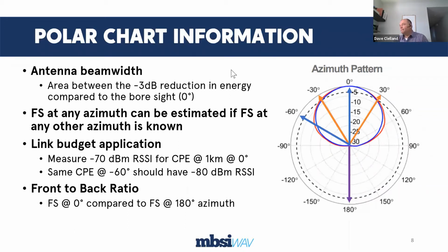So more graphically then, let's take a look at this typical pattern up close. This happens to be a KP performance antenna, by the way. It's a 4-port, 65-degree dual slant sector antenna that we're taking the measurements from. So we have here the azimuth pattern of this antenna, the left and right slant again. Remember, when we look at it up closer here, we see that the cross polarization is nearly zero